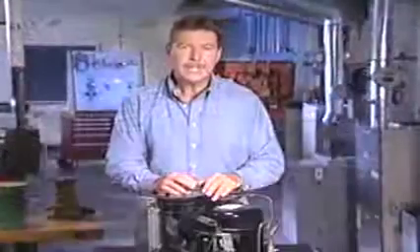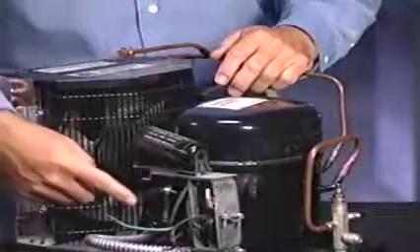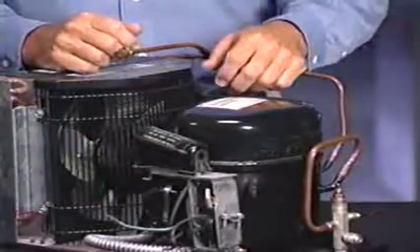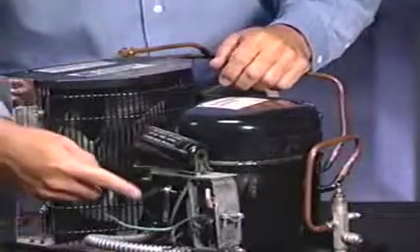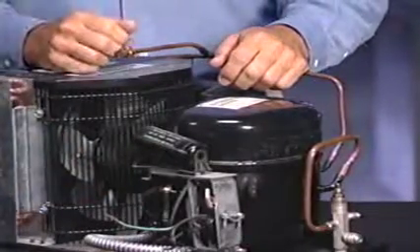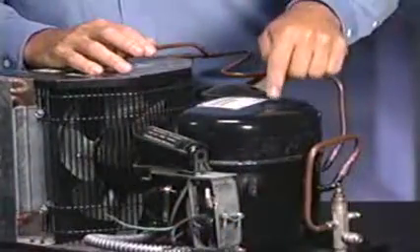The motors inside these compressor shells are surrounded by both refrigerant and oil, so it's important that there's no electrical sparking inside the compressor. Sparking can cause a short circuit, as well as refrigerant contamination. For these reasons, any and all starting components are located outside the compressor shell.